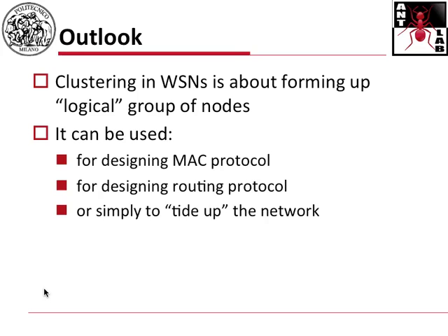And then I have to manage, though, in some way how these clusters are created, which channel is assigned to each cluster, and how to manage the inter-cluster communication. Okay? So, to ease up the design of MAC control, to make it more efficient in terms of collision probability. Clustering is, in many cases, highly coupled with routing.